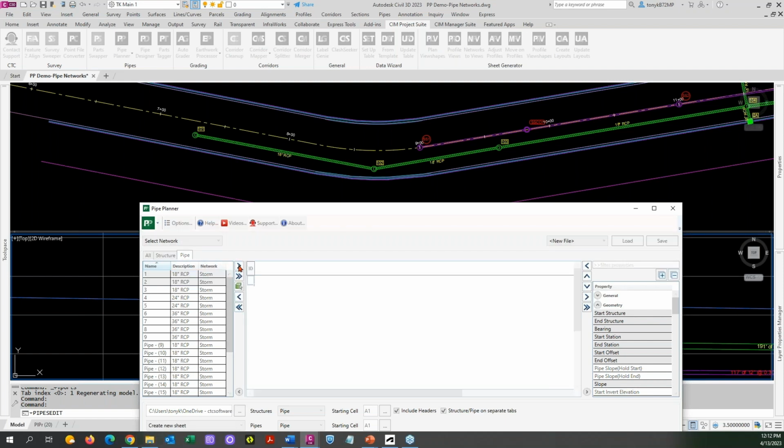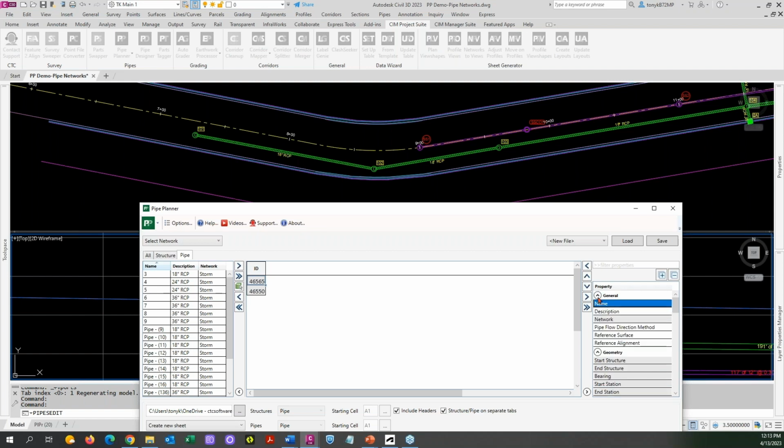So if I pop those 2 over, the first thing you're getting is the handle. Everything is controlled by the handle IDs right here. That's how it knows how to make updates to our parts. That's why these are not editable. So let's come over here and push the name over, and push the description over. The description is coming from when you set this.